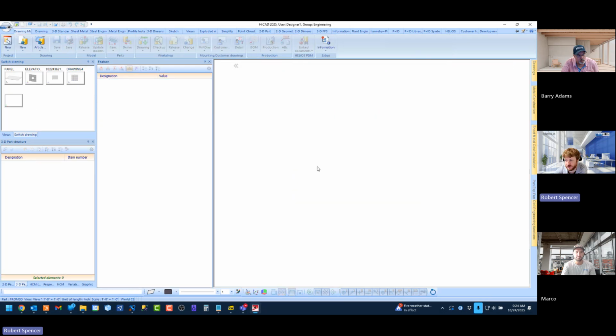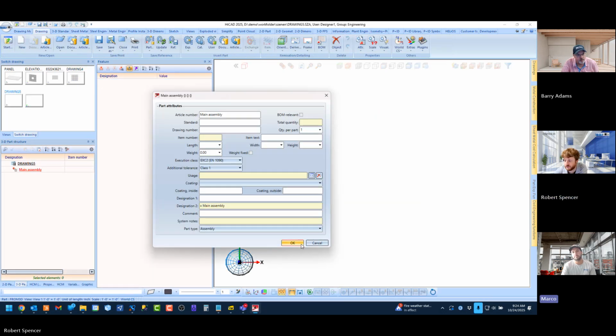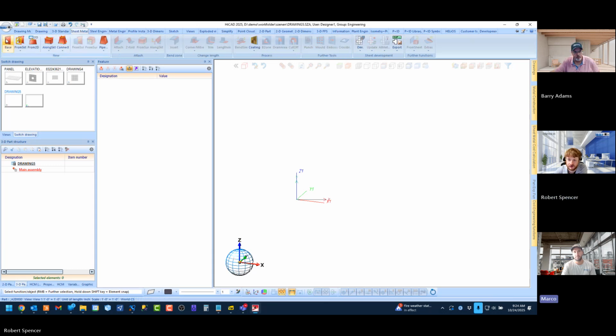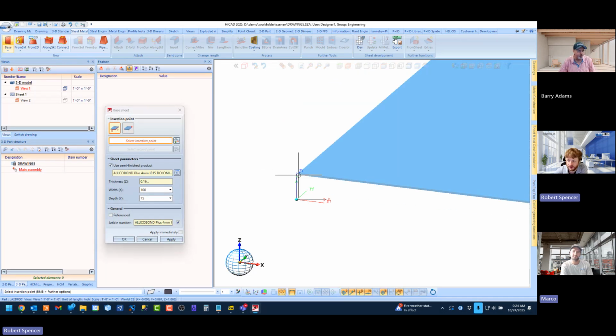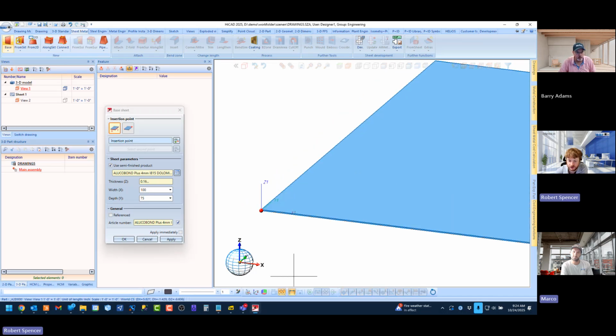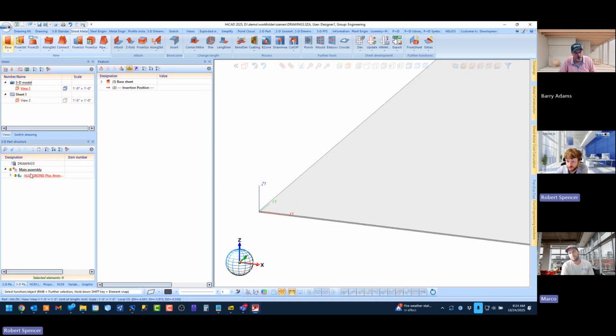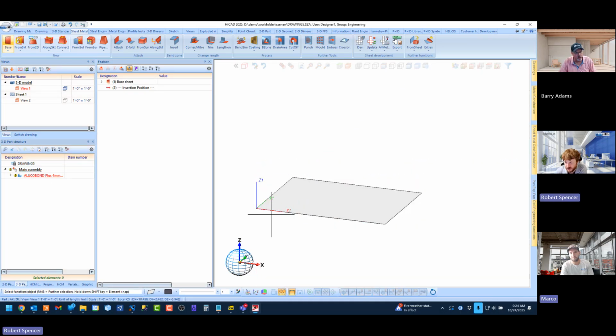So here's how I would have started this. Let's say that we say sheet metal. In this case, we said create base sheet. We could also do a sketch. It kind of works the same though. I say base, I pick my material, I right away say right mouse button, origin, and it goes right to it. And then you can continue working.